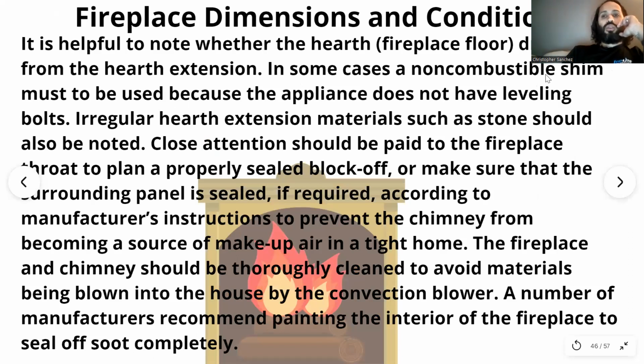It is helpful to note whether the fireplace floor drops down from the hearth extension. In some cases, a combustible shim must be used because the appliance does not have leveling bolts. Irregular hearth extensions, materials such as stone should also be noted.